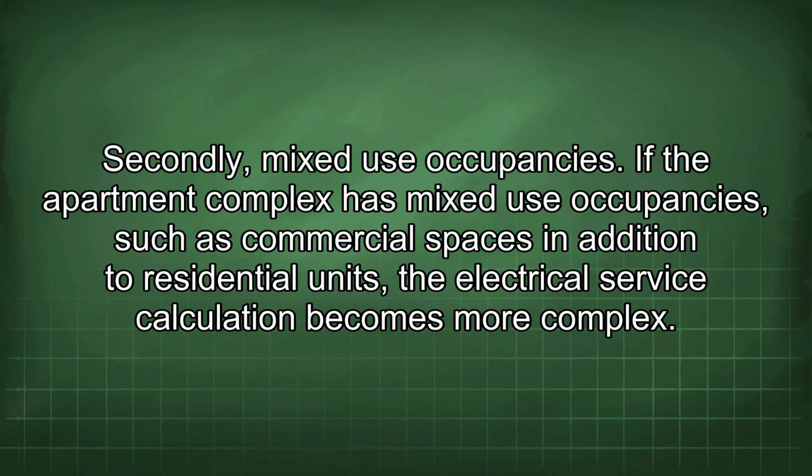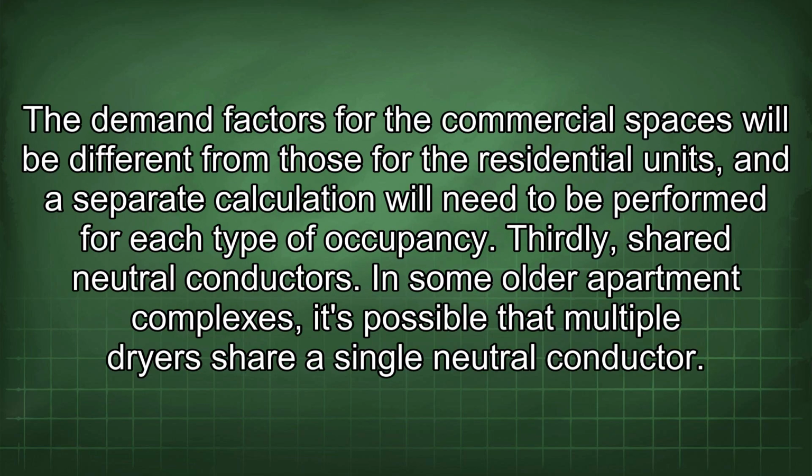Secondly, mixed-use occupancies. If the apartment complex has mixed-use occupancies, such as commercial spaces in addition to residential units, the electrical service calculation becomes more complex. The demand factors for the commercial spaces will be different from those for the residential units, and a separate calculation will need to be performed for each type of occupancy.